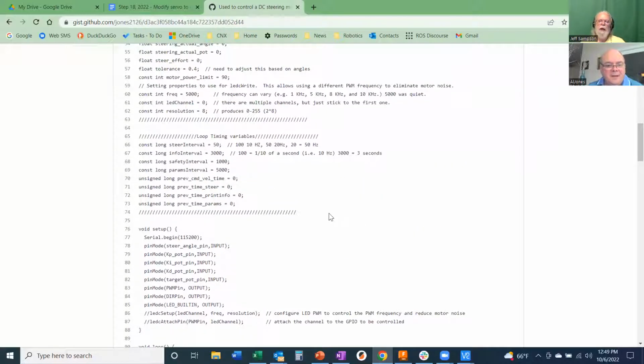Based on that comment, I would say the first thing to do is go down to the bottom where I said take those two lines, cut them out, and stick them in the other routine down there. Do that first, so you have something limiting your travel. Then set that safety limit so you can only go a little bit on either side of your zero position. Until you verify all that's working, don't set it anywhere close to your hard stops. Move it in quite a way so you have a very small range you're playing with, and you can verify that all that's working.